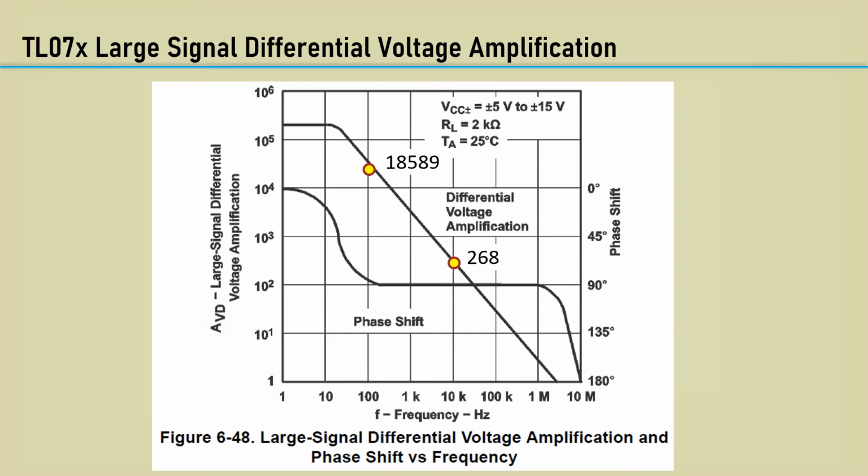The main takeaway is the reality that an op-amp may not have enough large signal capability to attain precise gain. Always calculate the closed-loop gain using the large signal amplification at the highest frequency of use. In many cases, where high gain and large signal is required, a set of cascaded amplifiers are necessary.